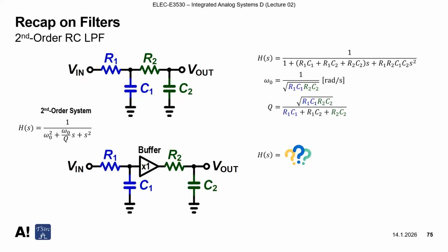Sorry? Sum of this part and this part. Oh, that was very close, but in the end, instead of summing them, we can think about multiplying. Yes, thank you. We are doing multiplication because, as we did for the Laplace transform or transient response, in the frequency domain we have to multiply the transfer functions to get the whole transfer function. So it is simply 1 over 1 plus SR1C1, times 1 plus SR2C2.